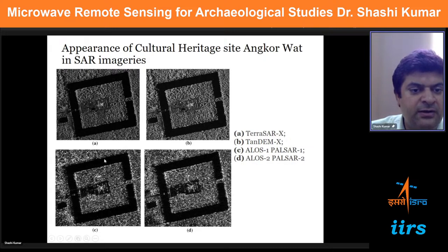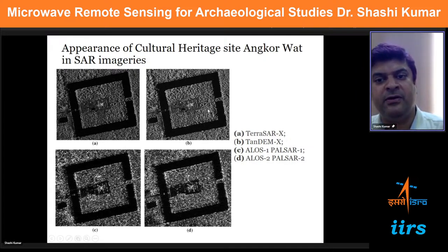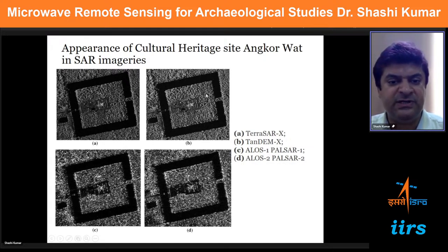But all the other features like the water body and scattering from vegetation could be easily seen. Now here, since this is a high resolution dataset, if you look carefully, the canopies could also be seen. We can also count the number of trees based on the canopy cover. So from here we can get several pieces of information, because the spatial resolution is high.